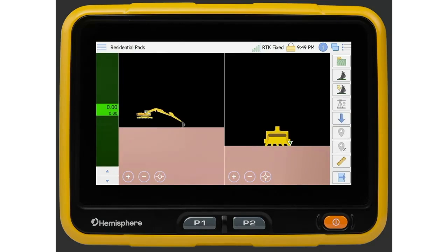If you think your customer will be using the 2D functionality of Grade Metrics often, then I would suggest adding our optional laser receiver. This will make it easier and quicker to rebench after moving the machine. Instead of tracking vertical machine movement using the above method, the operator would simply strike the receiver with a laser every time they move.